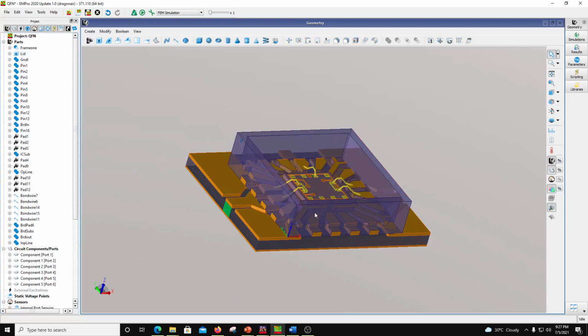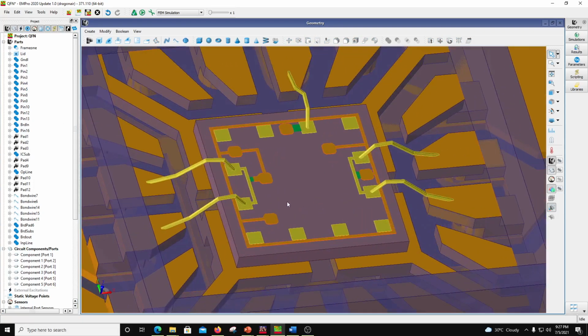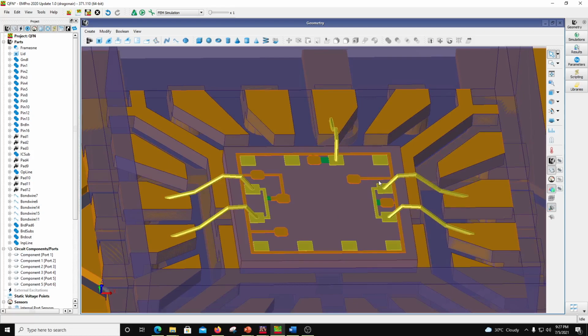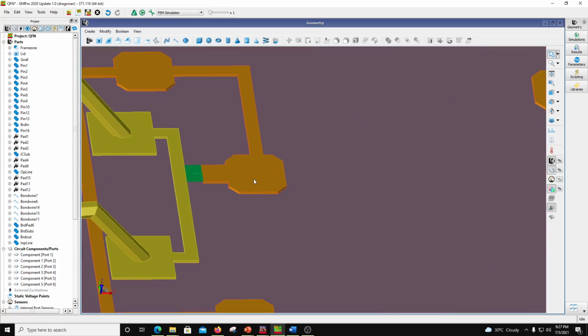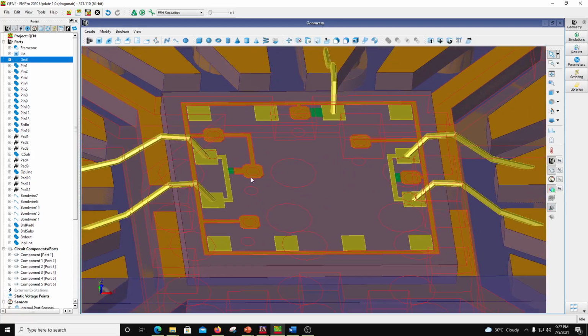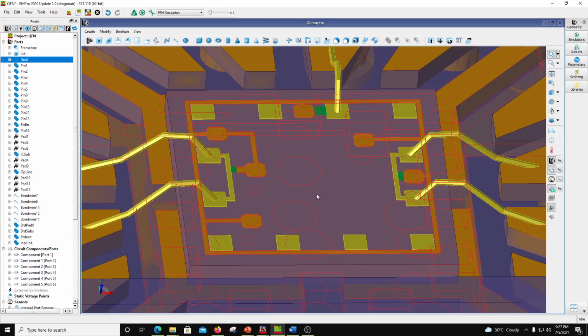Okay, so here I have thrown out all the transistors. All that's remaining are the pads for the input. So these 2 pads are for the input, these 2 pads are for the output, and if you see, they are ground reference to via here, so that's a via, right? So my world starts with imagining what a ground would look like. Okay, and the circuit can be built in between, right?